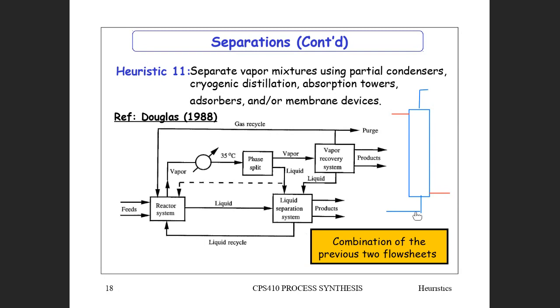This is the gas stream coming in with synthesis gas and methanol, and the methanol is going to be adsorbed by the water trickling down. And here we will have a water methanol mixture. And that can go into a liquid separation system to recover the loss of the methanol. The stuff that comes out here is seeing relatively pure water. So it will contain virtually no methanol at all.